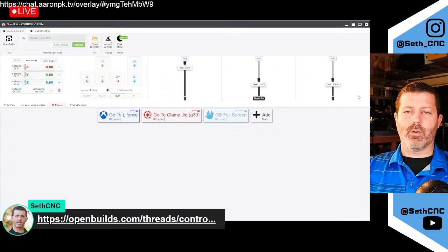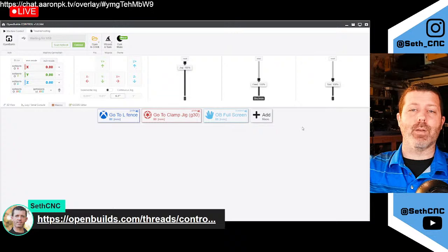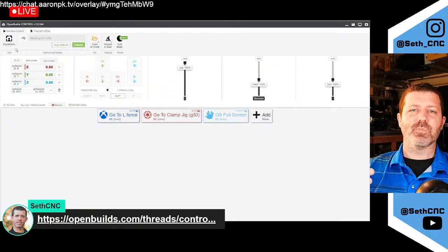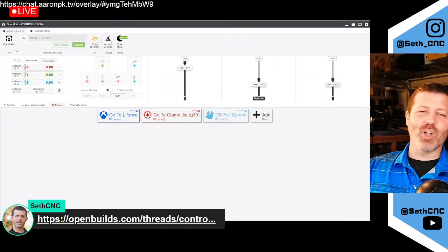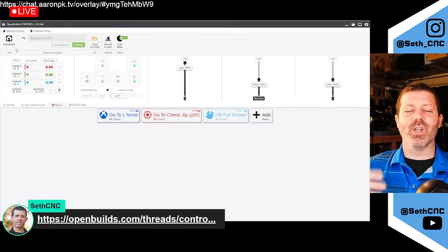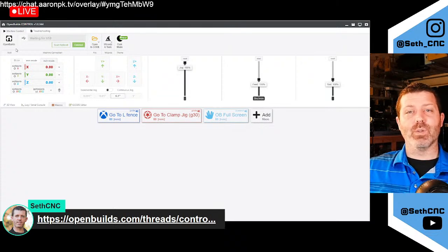This is the parking macro, right? So that allows you to define a position based off of home where you want the machine to park when you click this button. So let's say you do your carve starting from the front left position. Sorry, let me start over. Your machine homes to the front left, you then set X and Y zeros to the front left too, maybe. I usually prefer center, but regardless of where you set X and Y zeros, you run your carve, and if you're using something like Easel, it ends and goes back to that 0, 0 position.